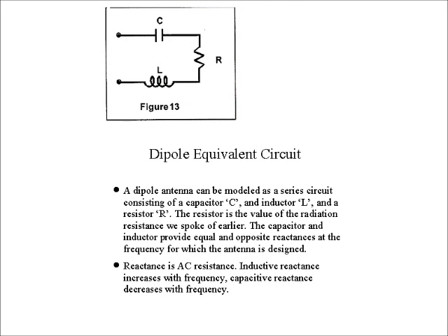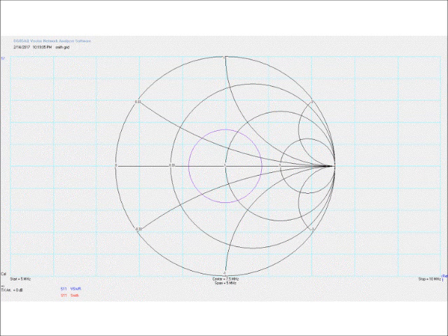We talked about reactance, if the antenna is too short or too long. We talked about this Smith chart thing that I'm showing you tonight. I only show that to you so that you can see that there is a relationship between antenna too long, antenna too short, feed point impedance high, feed point impedance low. It's a graphical tool that allows you to plot and graph that. It also is a great tool to show you how to match your antenna to your feed, which is a whole other science.